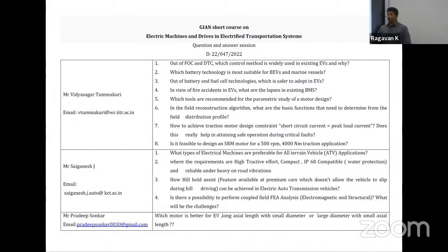LTO is expensive. So marine you can do, but LTO by definition is titanium. So if you can manage the money, which in marine application they might have the money for that. Lithium titanate, normally you're going for it a lot of times because it is extreme fast charge capable. So you're looking for very specific reasons.